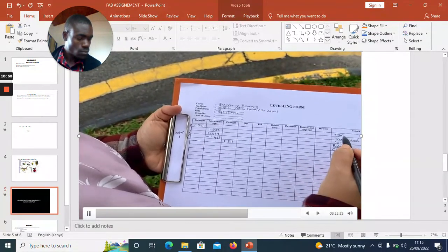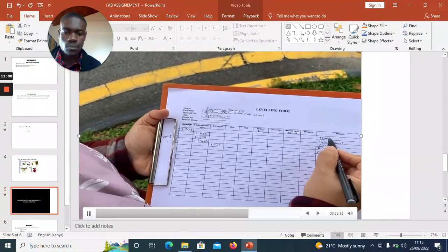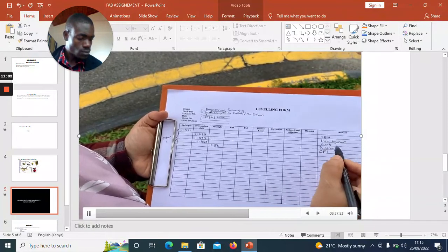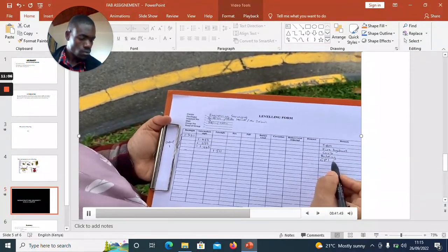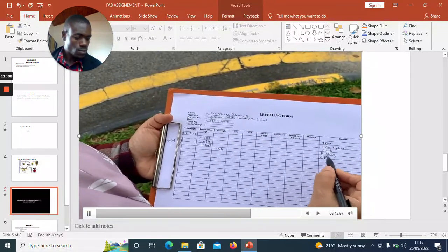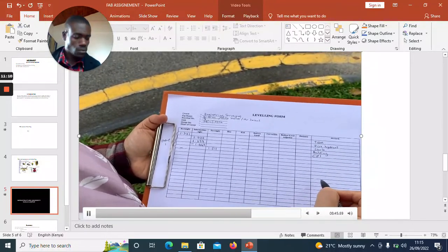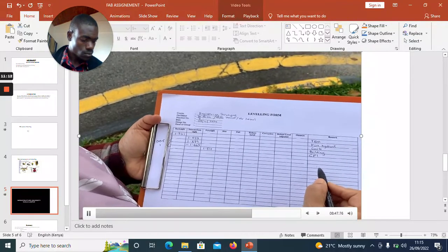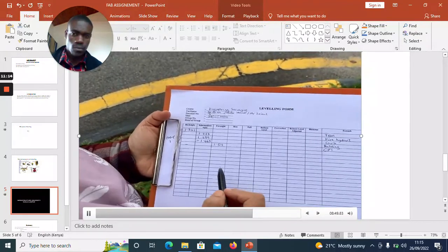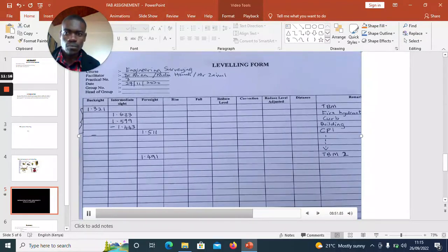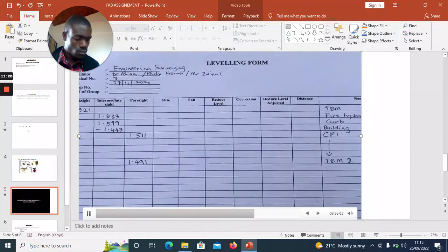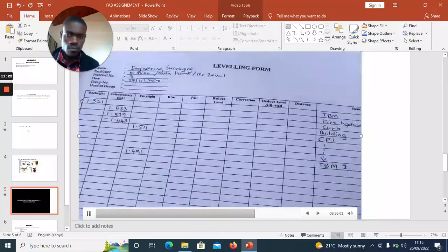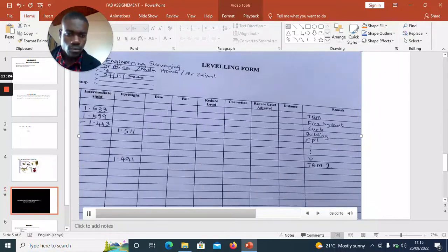Okay, just now the reduced level was transferred from TBM to fire hydrant to curb to building to CP1. Rest over there. Now pick up back CP1 to the other points that you are interested in to know their reduced level. Let's say we already finished our level run from TBM to TBM2, okay, and we are taking the TBM2 reading as our foresight.